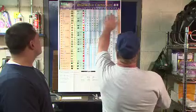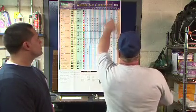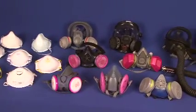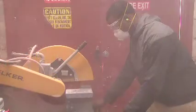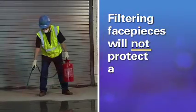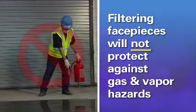Respiratory protection must be selected based on the hazard you will be exposed to on the job. Not every respirator will protect you against every hazard, so it's important for your employer to select the right one. For example, filtering face piece respirators may protect you against particulate hazards such as dusts. However, a filtering face piece respirator will not protect you against gas and vapor hazards like solvent vapors.